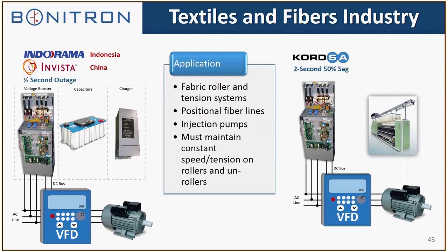This shows the difference in a lot of the third world countries. We'll use full outage ride-through. Ultracaps, this is a half-second ride-through, and it was due to a utility power switchover from plant power to residential power. They do that at the end of the day. They slam it over, it causes a half-second outage, and that's what we provided Ultracaps for. Now in the United States, once again, 2-second sags. We've done a lot with the fibers industry in the U.S. DuPont, which has now kind of been fragmented. One of them is Corsa that we work with, and that was a 2-second 50% sag that we backed up.